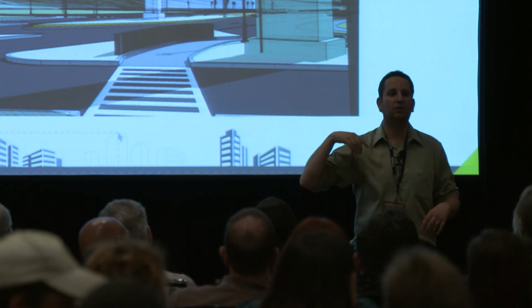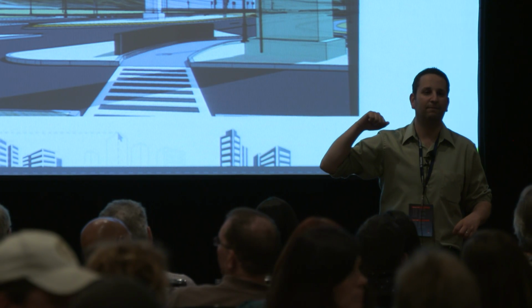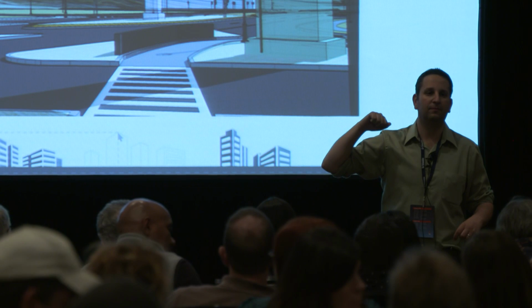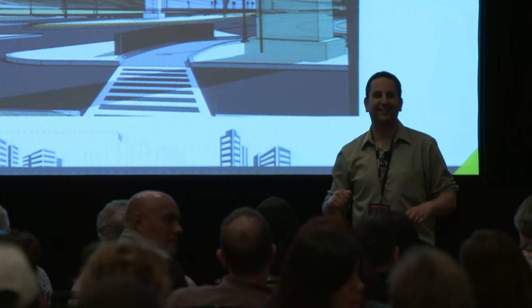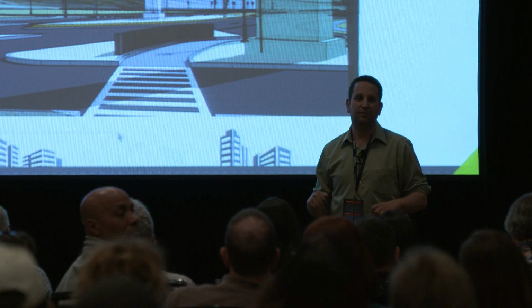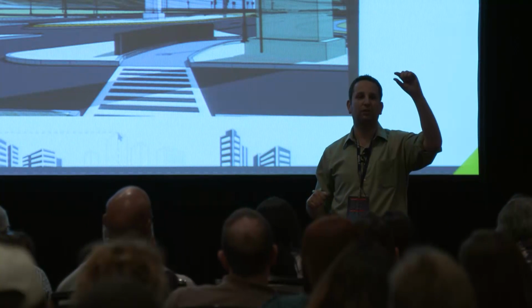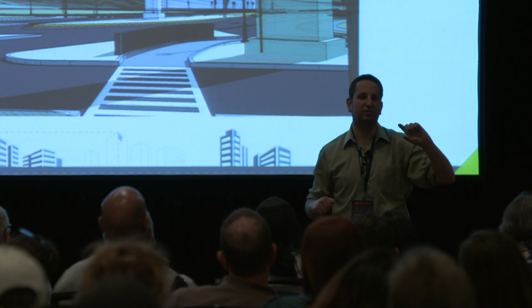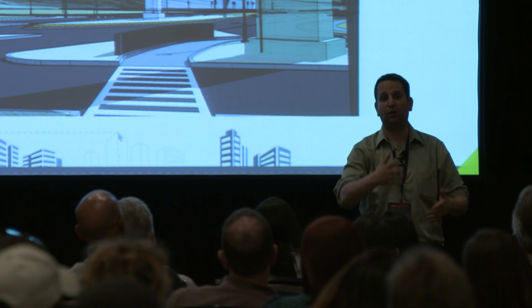Question? Hey Daniel, it's Kenneth. I've also found that if you're grabbing models from 3D Warehouse, a lot of times you can simplify them a great deal before you ever include them in your own model. That's right, because they have an option in 3D Warehouse to poly reduce. Is that right? Yeah. That's a great point. Thank you for pointing it out.